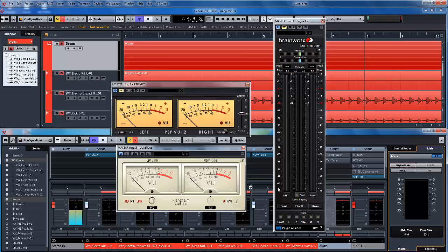On some meters, they'll go up to 96. I don't think we need that much extension. This one's 48. So what we're really concentrating on is the area around 0. When you have unity, which is the best signal to noise ratio at input, what we want to be able to do is to have that unity floating around 0. This is why we keep all our faders at 0. The idea is to use this fader as a fine-tuning mechanism as opposed to just moving it down a little bit and suddenly you get like a 10 dB jump. We don't want that. We want to be able to extend this fader as much as we like and only move over a few dBs.